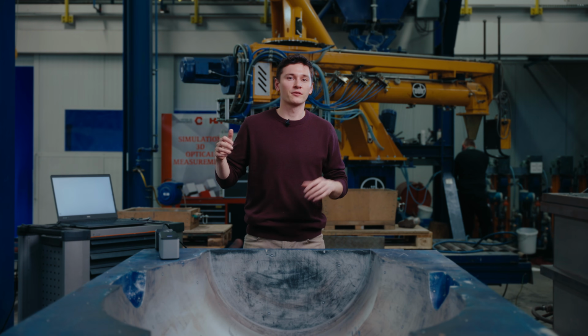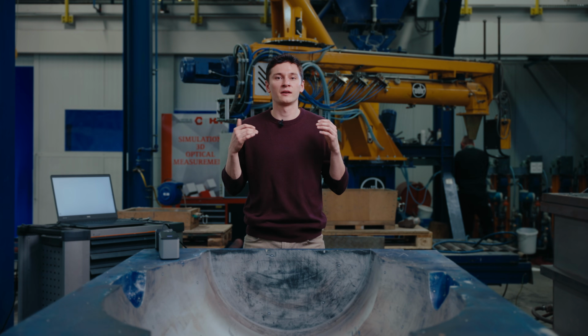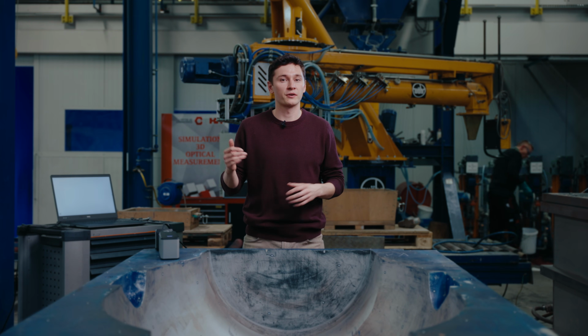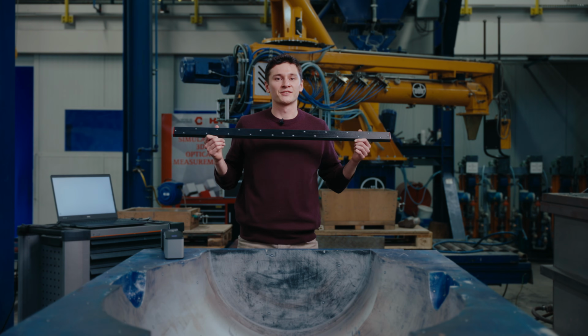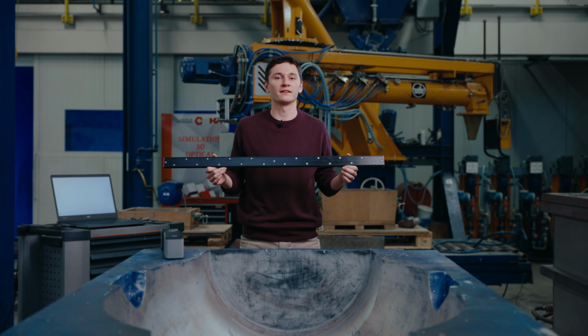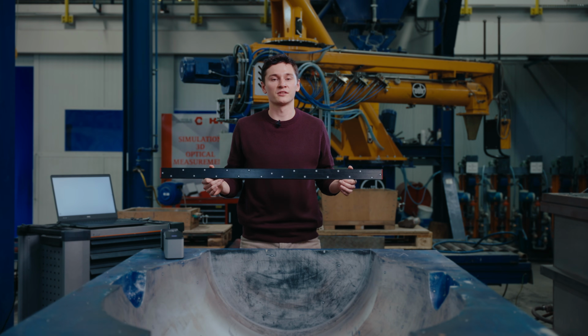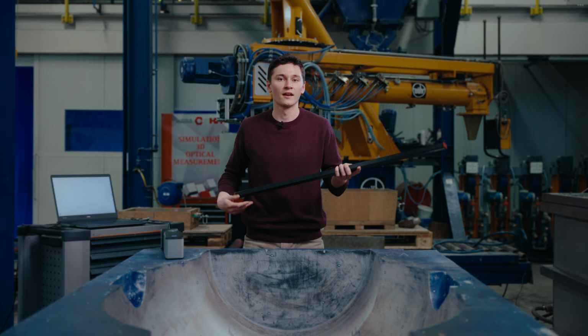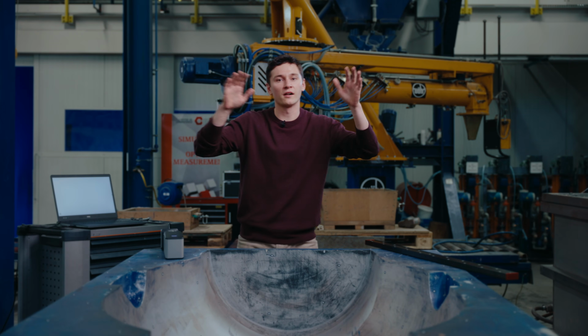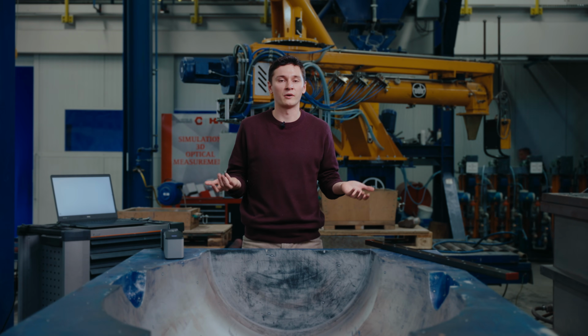With the satellite mode, we have developed a new algorithm that enables us to directly calculate the position of reference points on parts based on images. This data enables the software to create a stable backbone. The certified hyperscales help to greatly enhance the volumetric accuracy for larger parts if we compare it to the classical built-in photogrammetry from our previous generation of handheld scanner. When we place the scale bars in the setup, we can take the images from all around the part to make kind of an umbrella.